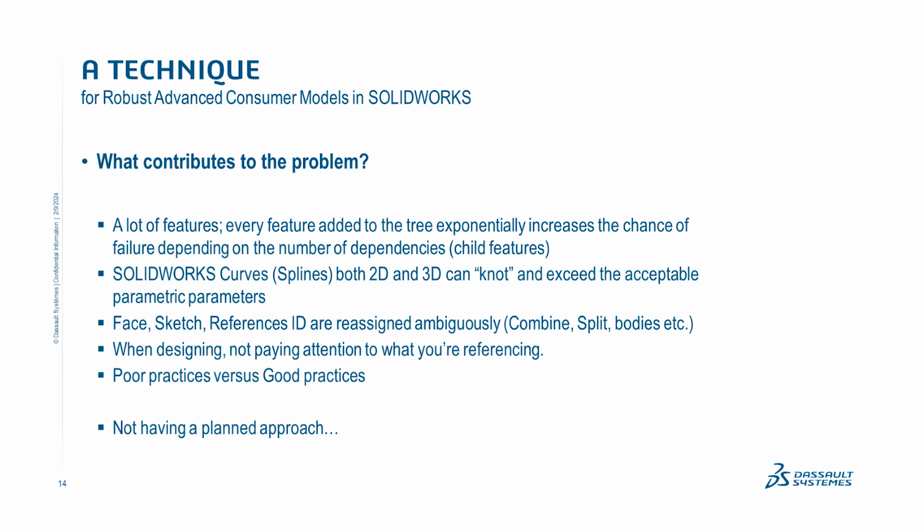Again, I talked about the curves. They can easily knot and over-constrain. And then I also alluded to the fact that surface modeling has many more IDs, or internal references, to track. Especially if you split a body or it's a surface that's split or trimmed, there's a lot more to consider to parametrically associate with.